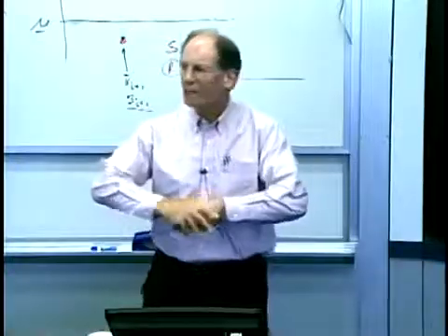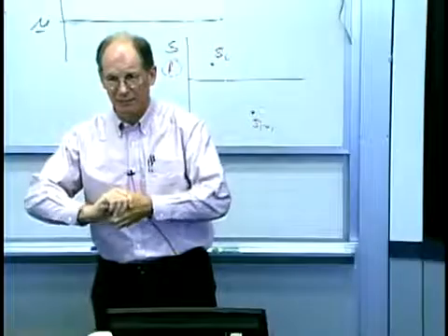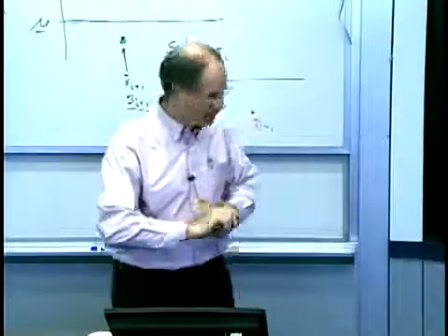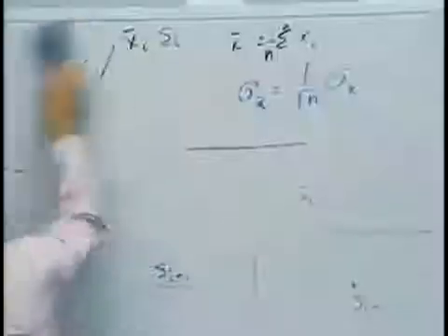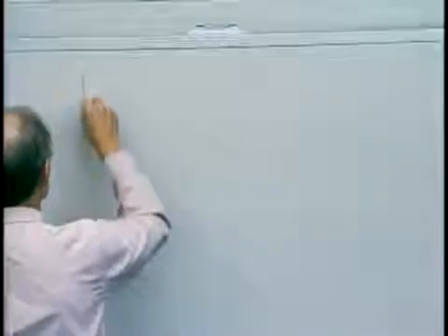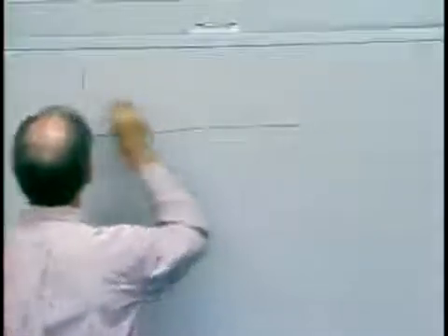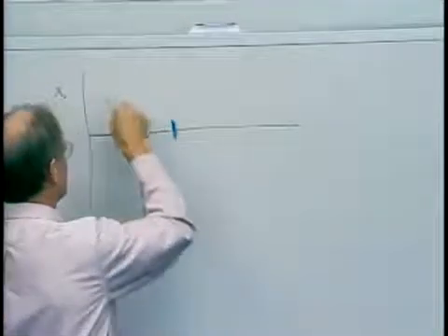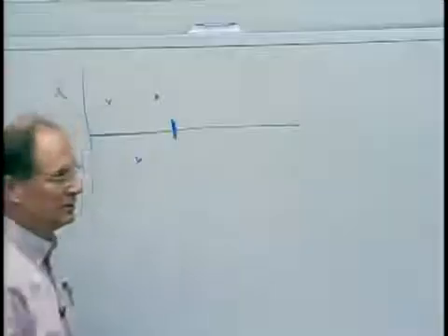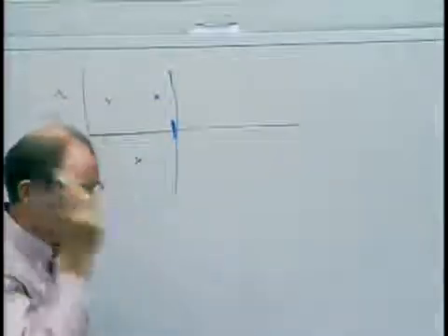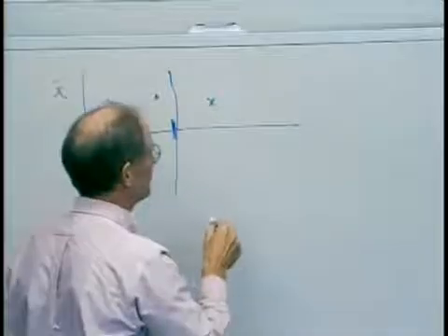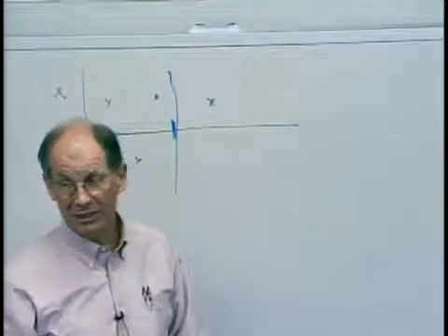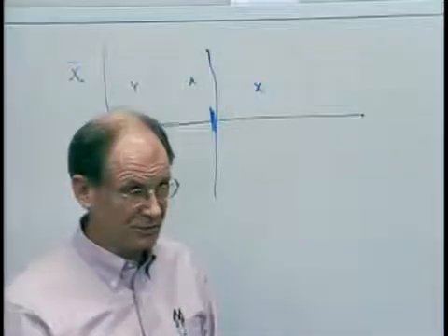Okay, so how would I apply this Shewhart charting concept? Let me back up. What I'm trying to accomplish is this. Again, I'm in production. Let's just look at the X-bar chart. I'm in production, and this is now. I've got some data back here. This is now, and I took another piece of data, and I want to say, okay, is everything all right? Time to take any action?